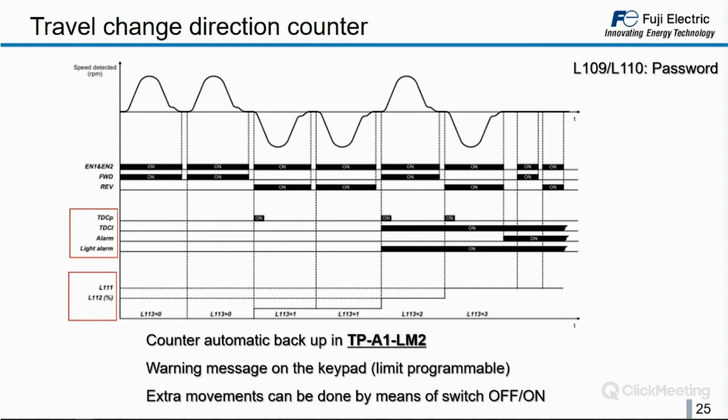This means that from this point, the suspension means is not okay to be used anymore, so we have to change them. As you can see on the graphic, even if the controller asks the lift to move, the inverter will not react. The inverter will trip an alarm, and this alarm will block the inverter until, by introducing the password and doing a certain procedure, we change the belt or the coated ropes, and then we can start the lift again.